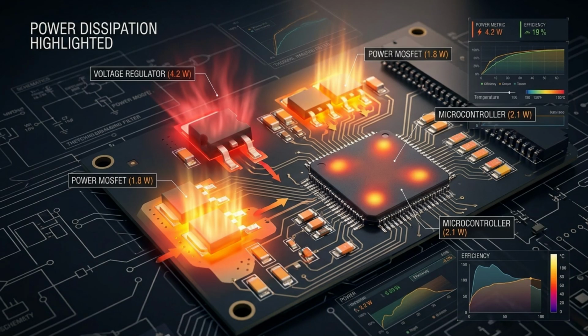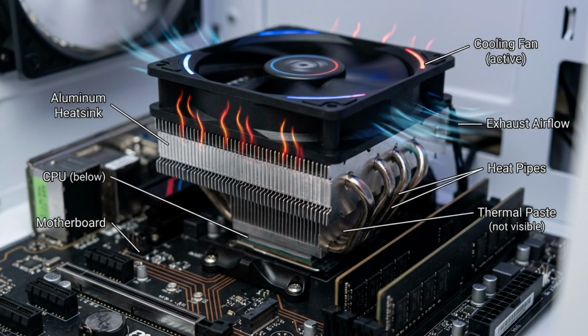Electrical power is a critical design parameter in every engineering system. Engineers use power calculations to size power supplies, select components, manage heat, and estimate system efficiency. For example, every electronic component has a maximum power rating. If too much power is dissipated, excessive heat may be generated, causing damage or reducing reliability. Power calculations also help engineers design cooling systems. High-performance processors, RF amplifiers, and power electronics often require heat sinks, fans, or advanced thermal management techniques.